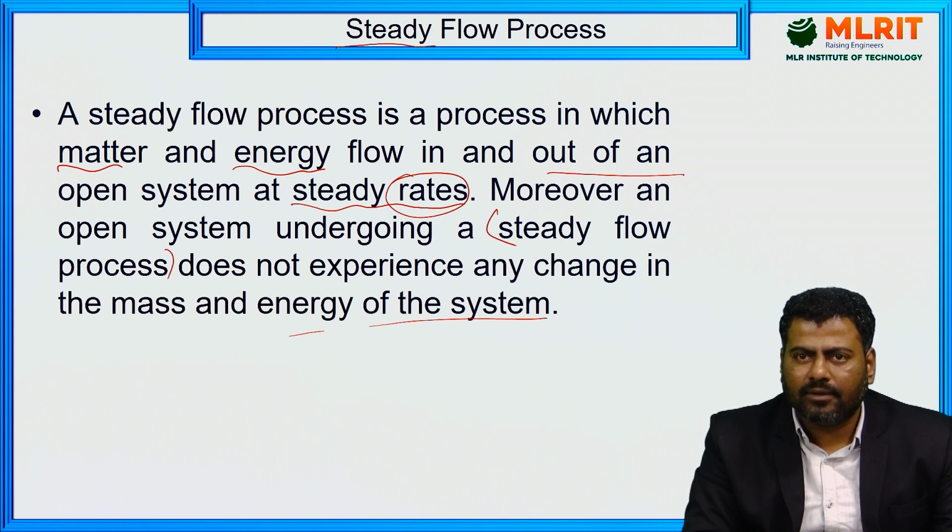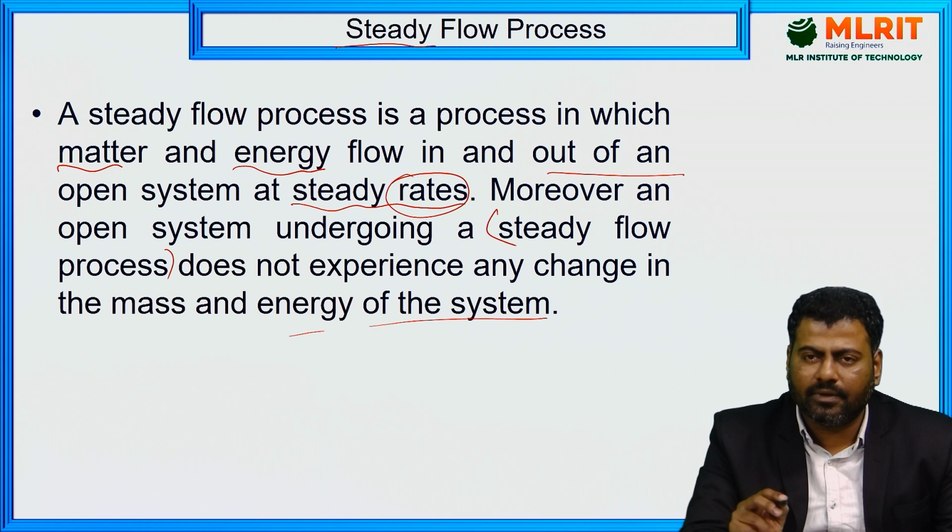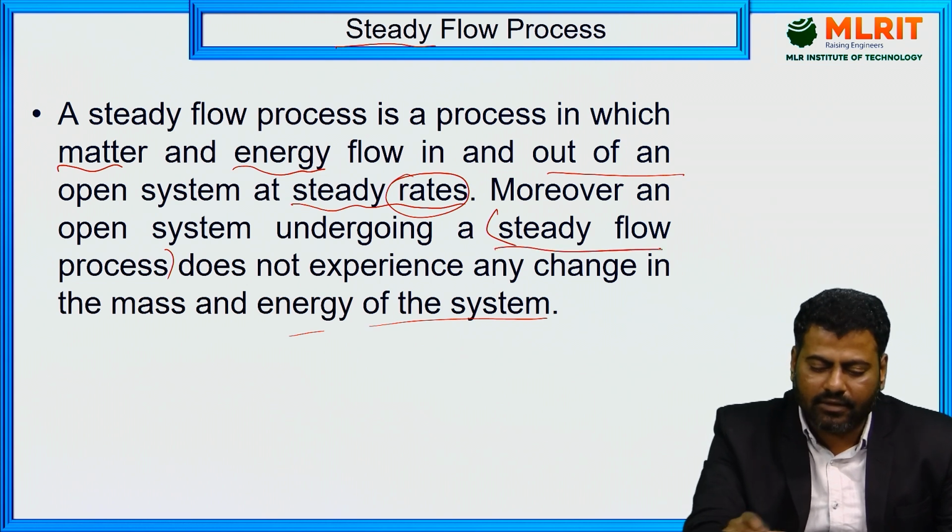This phenomenon is similar to the closed system. In the closed system also we considered mass equal to 1 kg. Similarly over here also we have considered mass equal to 1 kg, but we have the flow work done. So these energy parameters I am supposed to consider. Got it? That is why for simplification purposes we have these steady flow processes.